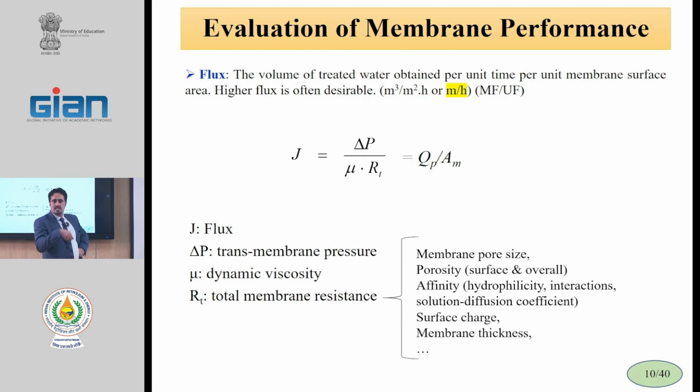With reducing membrane pore size, passing is hard and problematic, and with reducing pore size, the resistance increases. Porosity. Porosity is the free space in the membrane body or on the membrane surface. With an increase of porosity, resistance reduces. High porosity, high flux.